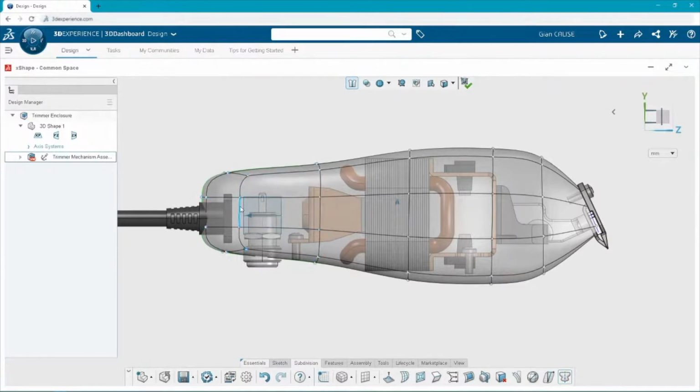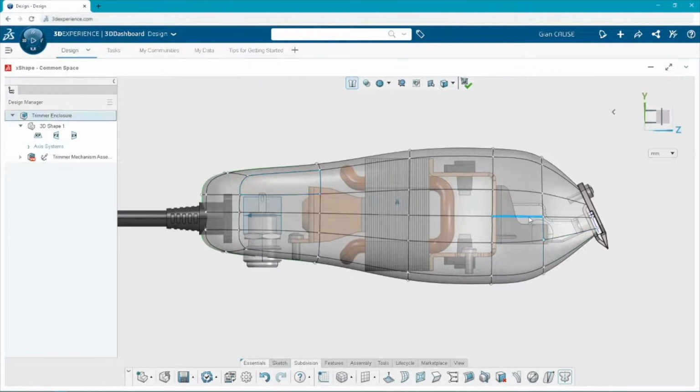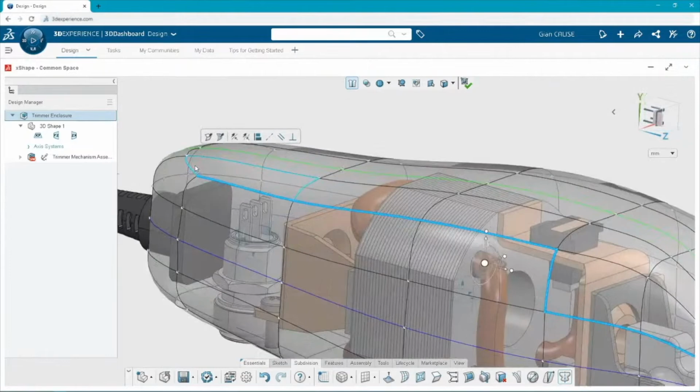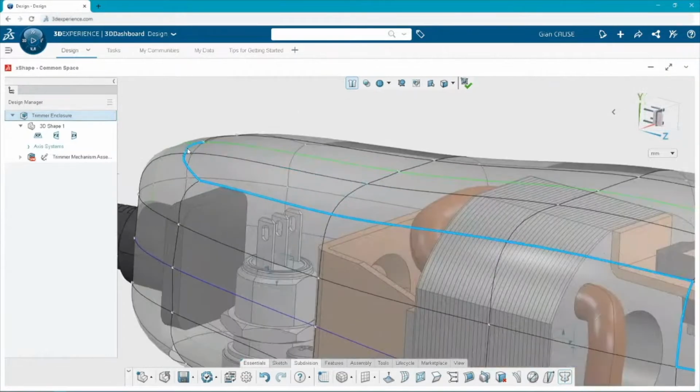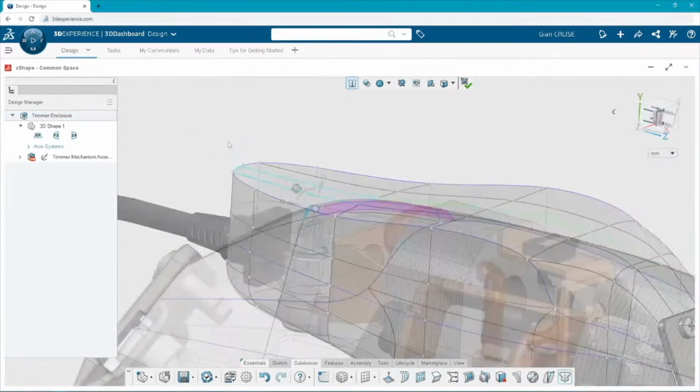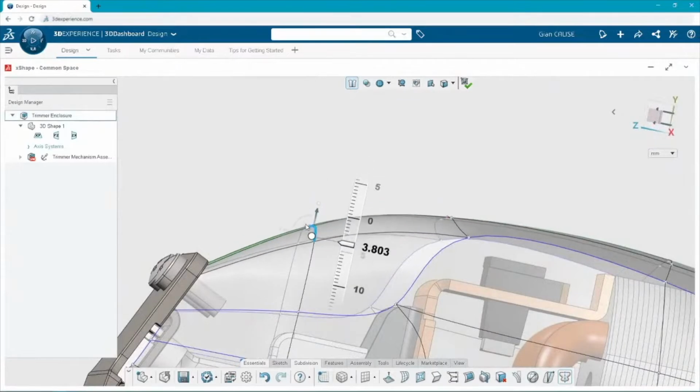This is going to be an injection molded part, and we're not going to do everything to prep it for injection molding, but we want to be smart about how we model this thing so that when the time comes, most of our work is already done. So that's why I'm going to add a crease around this whole side of the model so that we can get the draft that we're looking for, but you'll see more on that later.